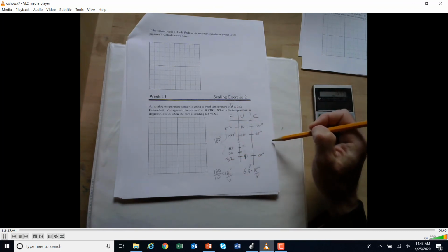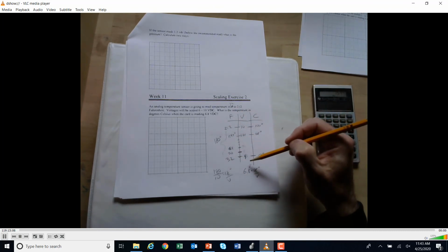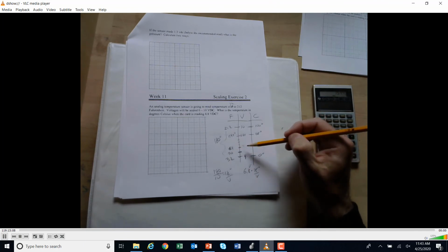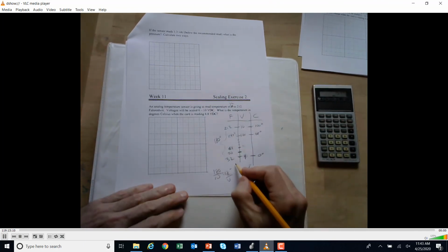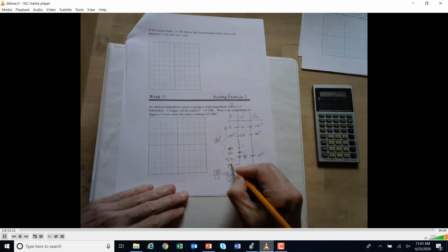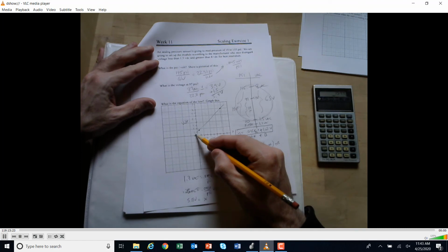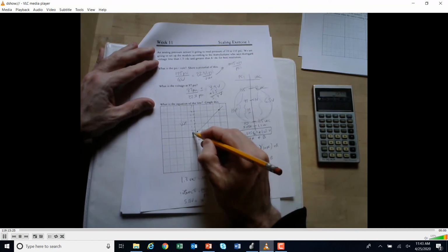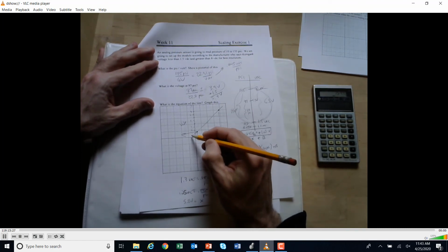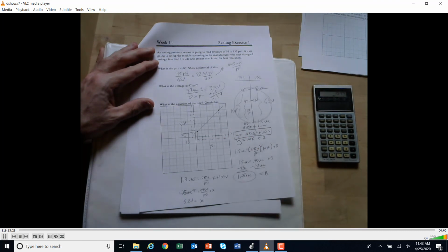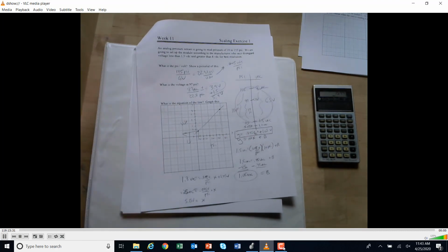So you just want to be aware and understand the math of how the computer is ratioing all these, especially when I come and I say, hey, at 20 degrees Fahrenheit, what's the voltage? Now that it all falls apart all of a sudden, you have to go back and get the slope of the line so that you can work backwards from the set point to get to where you want to be. Okay.